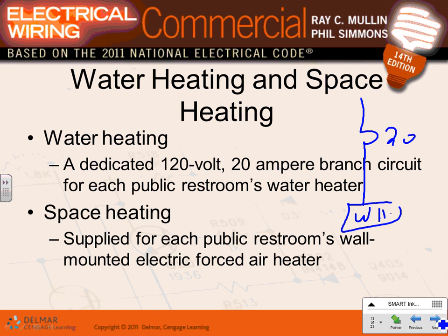And then they also have a space heater, same thing, 120, a space heater, number 12, and 20 amps. Typically, these are all number 12, 20 amp single phase, right? Typical of all these space heaters and water heaters in the bathroom. If you're building a small building, guys, and you don't have a central water heater, you can centralize it. So this is one way of having water heaters. Take the water heater right into that location.